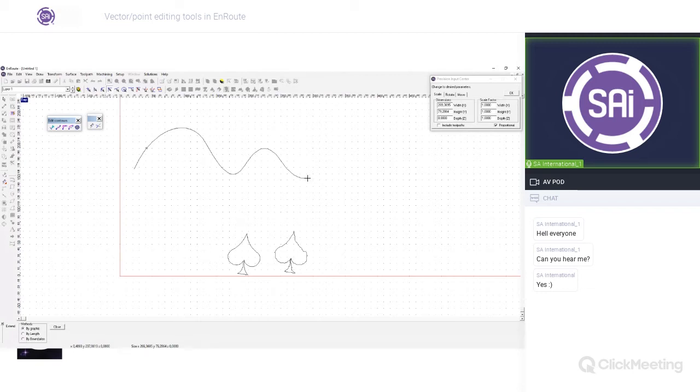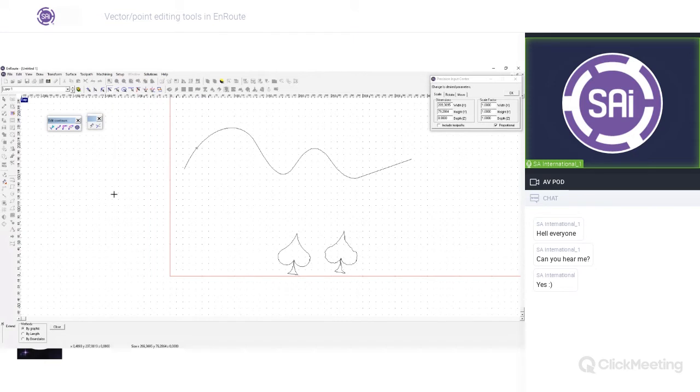So by graphic, you would simply just have to click and drag, and you'll see that it will follow the last direction of the curve. And then clicking again will confirm your selection. By length here, you could set a fixed length of 50, for example, and then just click on sections of 50 on your contour.